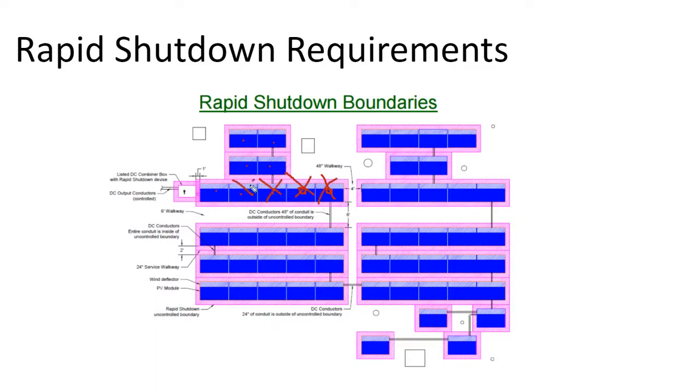So on a roof, it is wise to use module-level panel electronics despite the added failure points and slight cost increase. On the ground, detached from the building, the use of module-level panel electronics, particularly on an unshaded solar array, is less important.